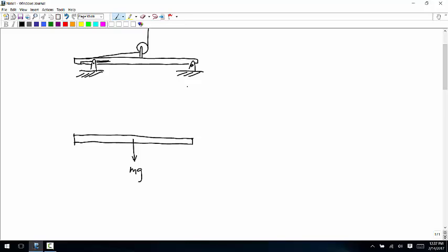So over here, there's a pin joint. I think I've stressed this before, but really the best way to approach it is just remind yourself that you're not trying to really think about anything. Everything's just like a lookup table. Over here you see a pin joint. So what do you put on the body with a pin joint? It's always just an unknown force vector. And so just put that in like this.